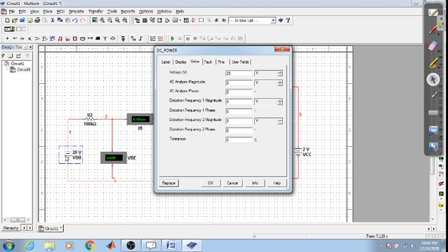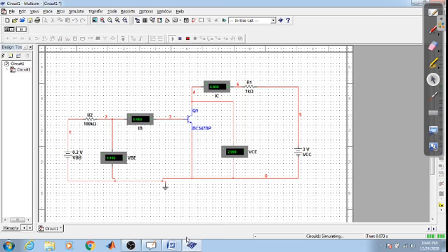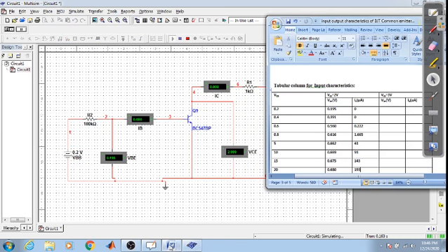And now you vary the VBE. You vary VBE by varying VBB and check out VBE and IB. So stop this one. You make this 0.2. Click on OK. Run this. So VB is how much? 0.195. What is your current IB? It is 0.